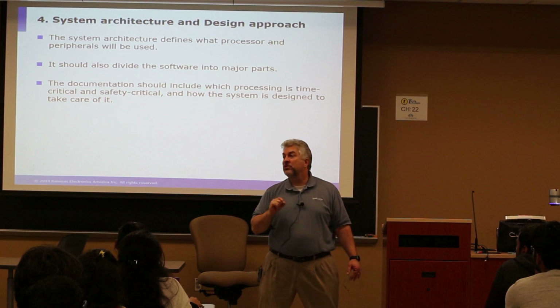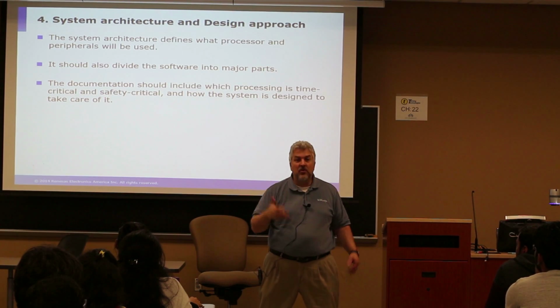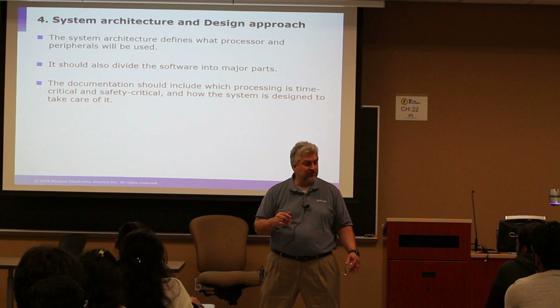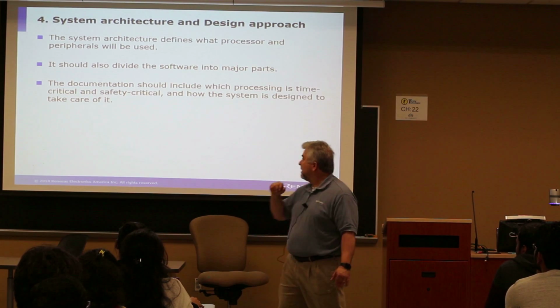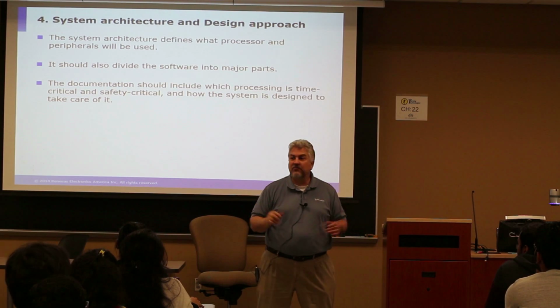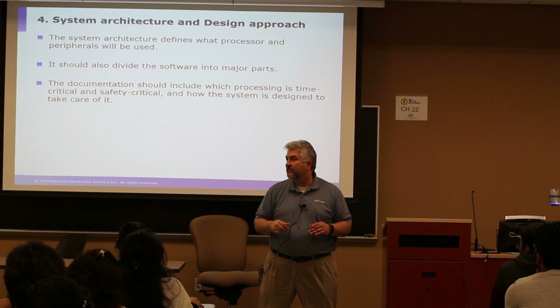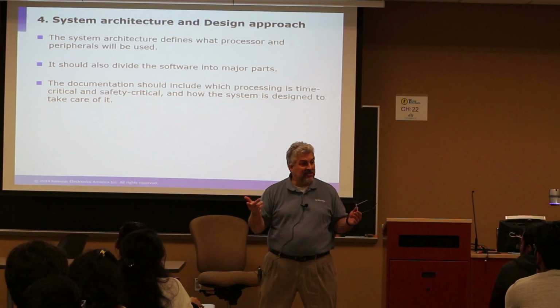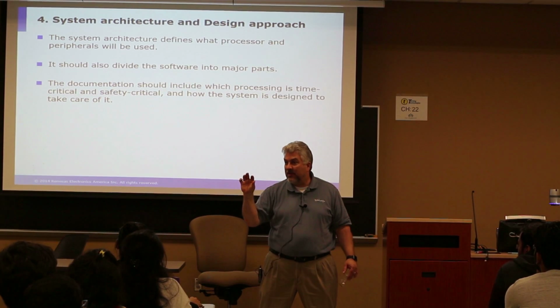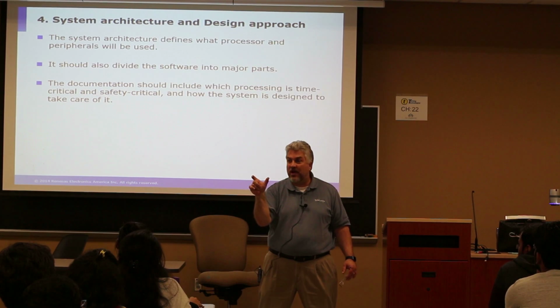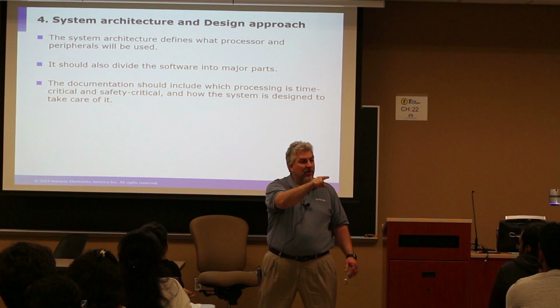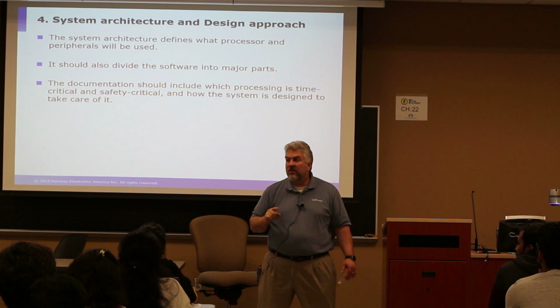And based on our tools, it will be the MSP 430 because we have the existing tools and expertise. And peripherals. So what kind of peripheral do we definitely need? An LCD, correct? How many characters wide? 8. We already said that in the requirements. And then we had buttons. Anything else?